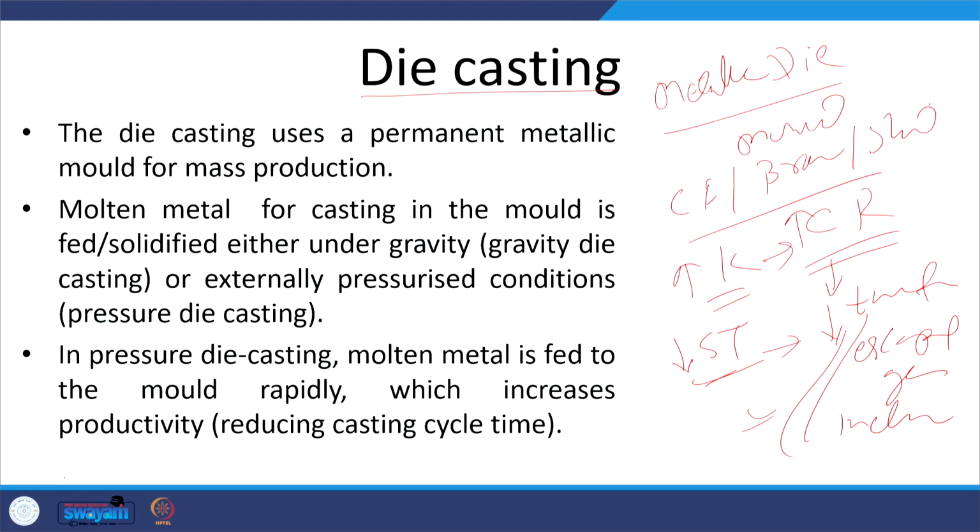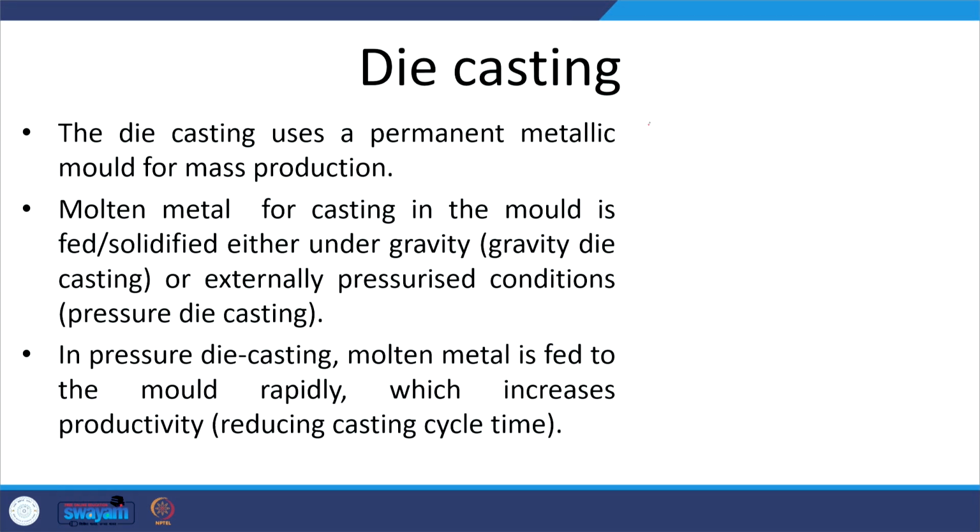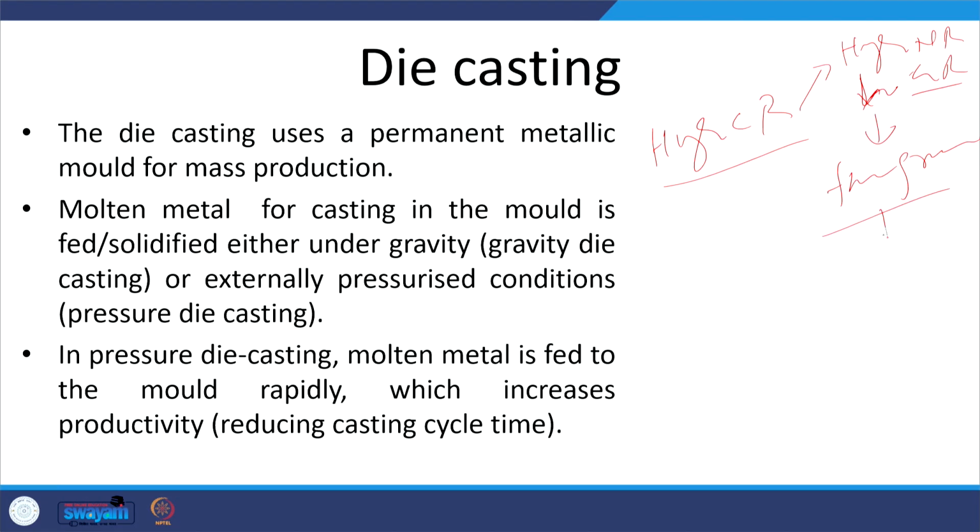But on the other hand, the high cooling rate which is realized during die casting results in a higher nucleation rate and a low growth rate, okay, and this in turn results in a fine grain structure, which in turn results in a good combination of mechanical properties.